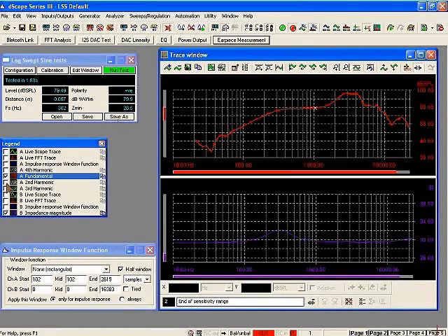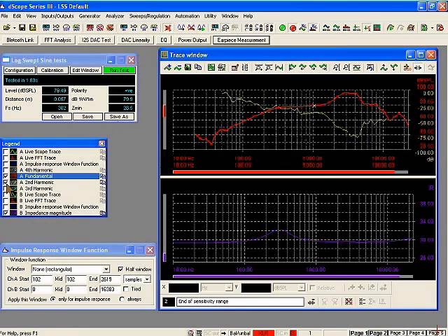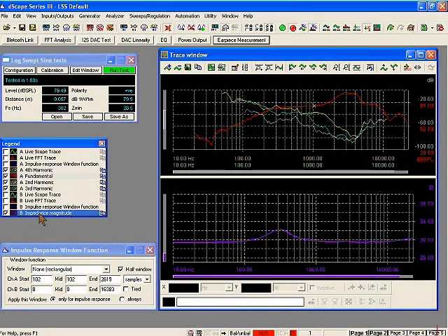In addition to the fundamental, we have the second harmonic distortion response, we have the third harmonic, the fourth harmonic. We can go higher if we want to. I'll introduce you to how we've derived these results in just a second. But I just want to explain the fact that on channel B here we also have an impedance measurement. So this is the electrical impedance of the transducer loaded into its chassis, in other words the Bluetooth headset chassis.